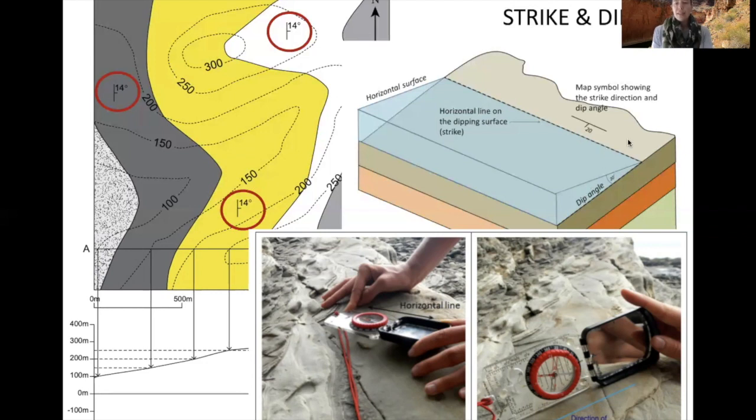If we look at this cartoon diagram in the background, this long line is the strike direction. The strike direction is measured using our right hand rule. If you take your right hand and set it down on the rock surface, your fingers are going to go down the dip of the rock and your thumb will point in the strike direction.